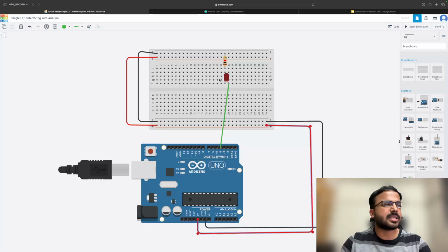Peripherals for us here were LED. So we connected this to the 19th row. And now we are connecting a resistor from the 0 volt row. So we are giving 0 volt to this part. This is your cathode. We'll see this in detail, but this is how we are getting much more flexibility to connect, with the breadboard.